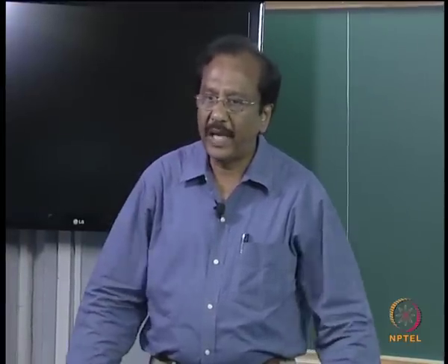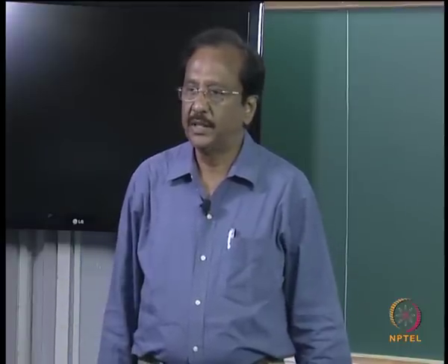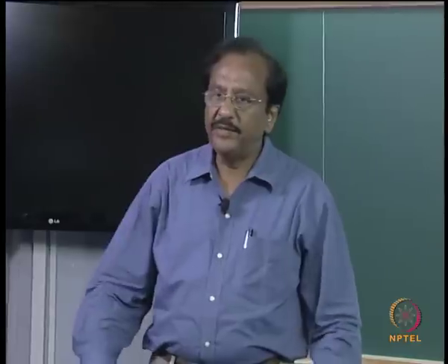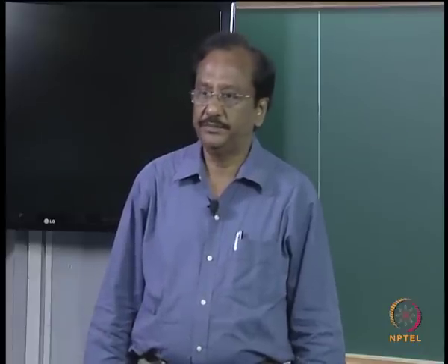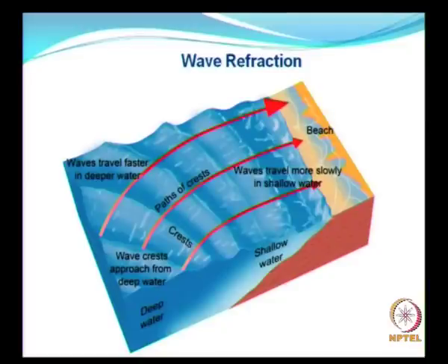If you want to plan for some kind of a structure or a development of a harbor along the coast, you need to know how the wave is going to behave, even before you construct something there, for a given deep water wave height and deep water direction, how this transformation takes place.